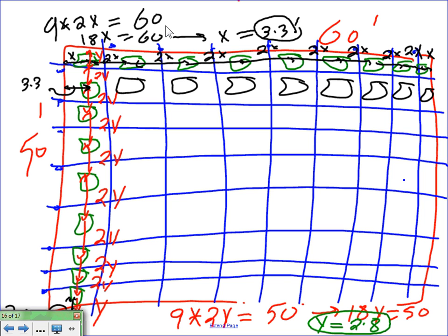Please understand the definition of slimline lamps, S-L-I-M-L-I-N-E. These are, back to your question, Tao, associated with the single pin base for fluorescent lights. And by the way, the single pin base goes with instant start. They say it's associated with instant, not rapid start. Rapid start is different; instant start has a single pin. So slimline lamps are more expensive. Yeah, instant start. That's probably why we don't use them that often. So slimline lamps are associated with instant start and one pin base.